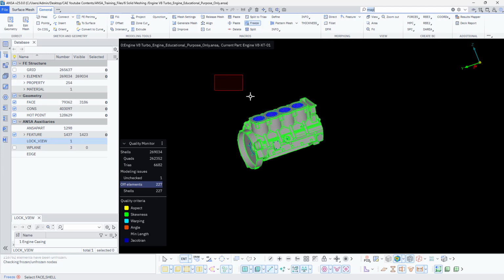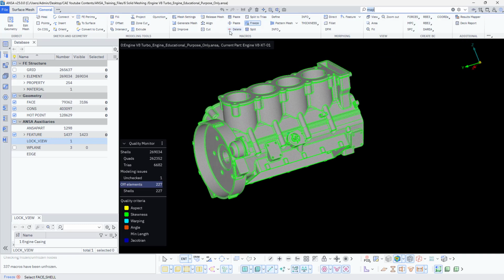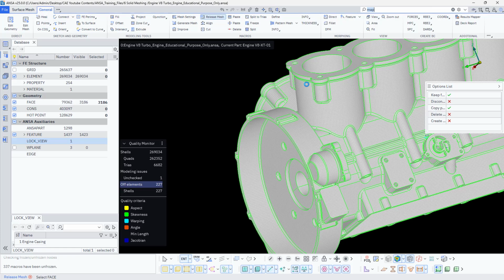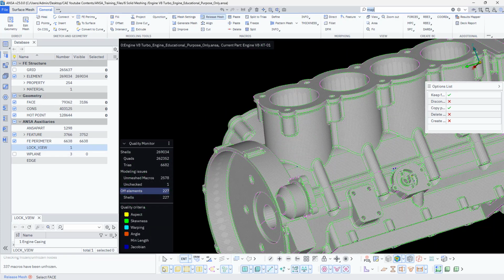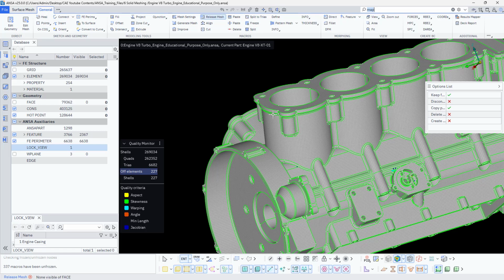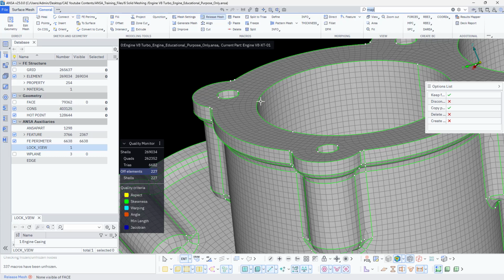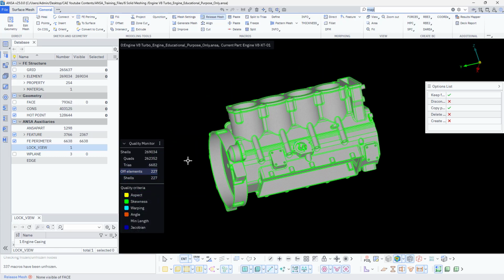right click, hold and drag. Now it is unfreezed all the elements. Now what I'll do is I'll go with the release mesh, and then I'll just release entire mesh. Now you won't face that issue, right? Could see everything is intact. There is no discontinuities. Okay. Now we have the off elements.